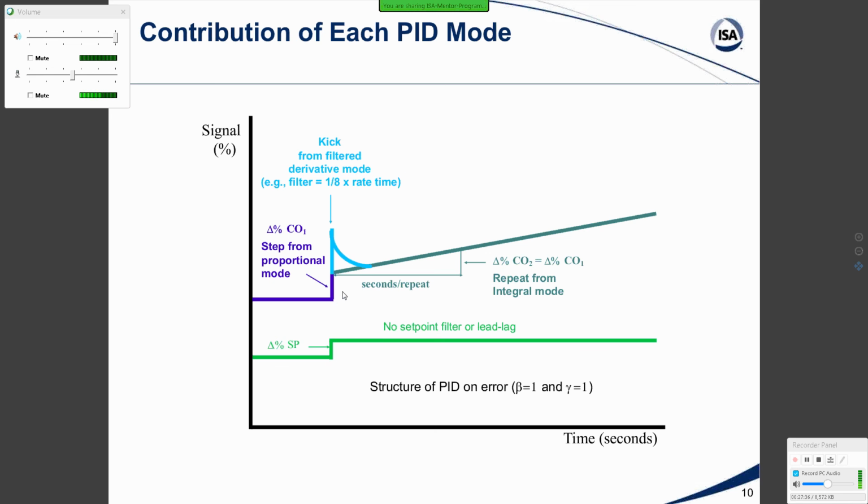That would correspond to a gain of 100. Now, I'll get into some war stories probably in November that will give you some very interesting scenarios where people didn't realize this, and they went from a controller with a proportional band of 100 and didn't realize they're now dealing with gains, and that would be a gain of 100 that they're putting in there.